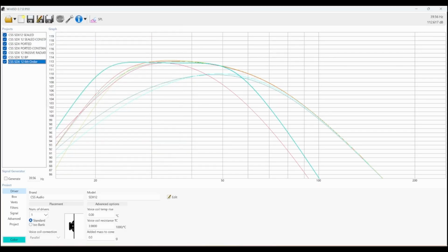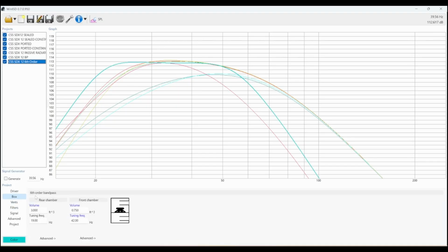By shifting like that, an enclosure of higher orders, 6th order being more so than 4th order, more so than 2nd order, ported and sealed, means that your tuning could drastically be different than what your predicted response is. Do keep that in mind when it comes to higher order boxes, it might be not what you modeled, because the specs might be just different enough to start screwing things up.